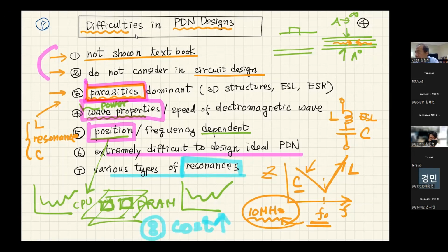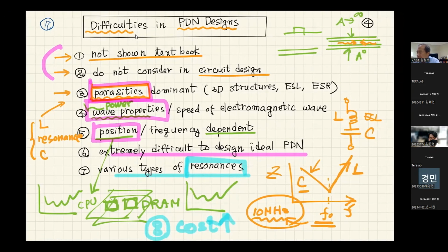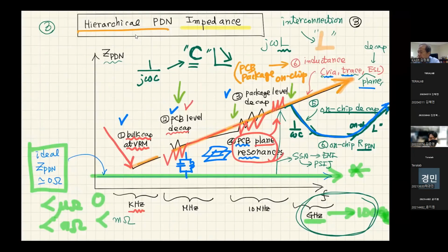To overcome number 3 to number 7, we have to minimize the resonance inductance and has to put decoupling capacitors as close as possible. And we also have to put a good amount of engineering resources on power integrity when we are designing PCB and packaging and chip together.